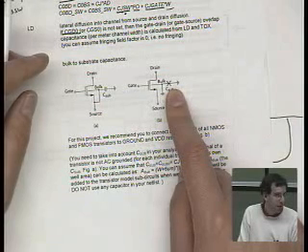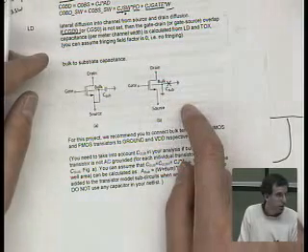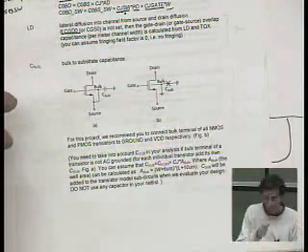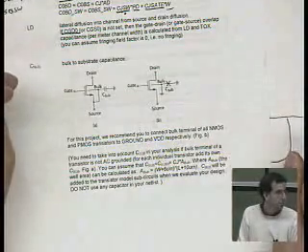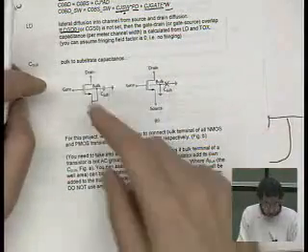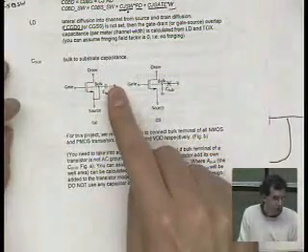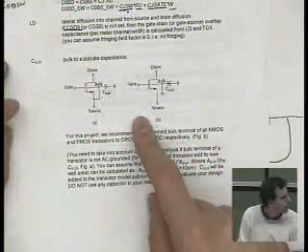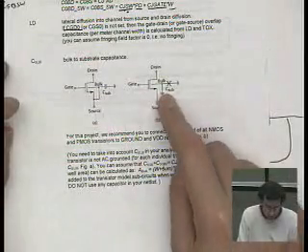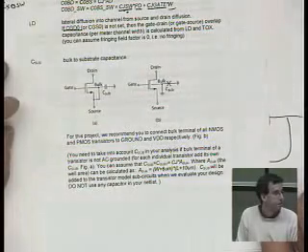Okay? Yeah? Would you also get a depletion capacitance then? If you tie your bulk to your ground, you tie bulk to whatever your substrate is tied to. Bulk is your substrate. Yeah, but you still get the same depletion capacitance. Yeah, you do, but there's no signal going on it. Because now, and look, the thing is that the capacitance goes from the bulk to the universal ground node. Can you see this? Is this picture big enough to see on the screens? If the bulk is grounded rather than tied to source, that capacitance doesn't hang off your source node. Okay?